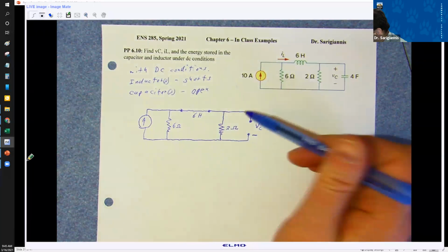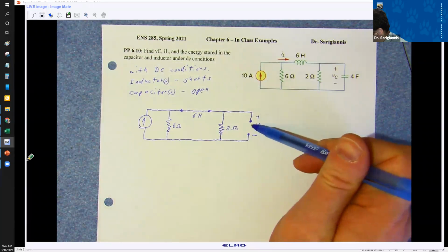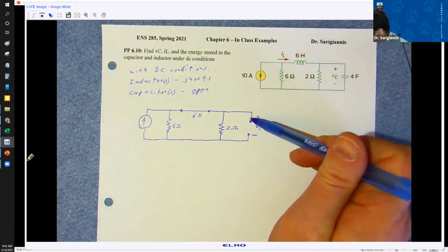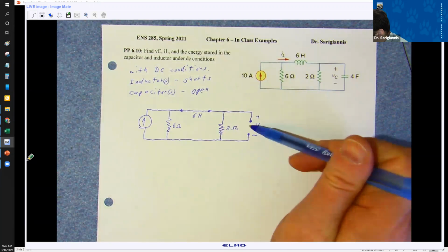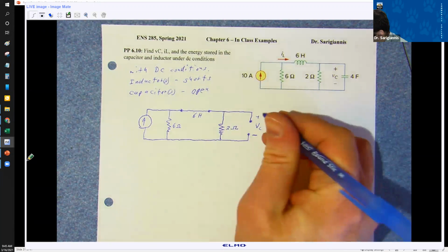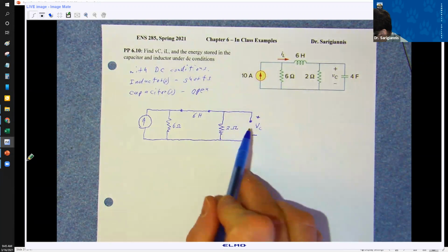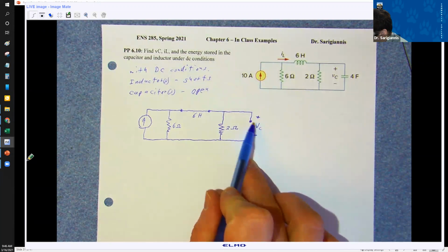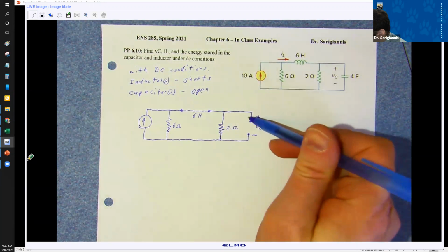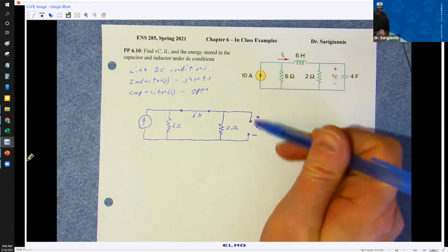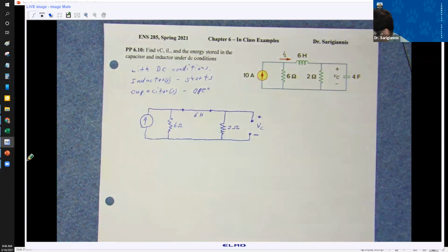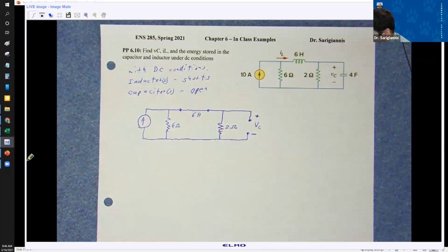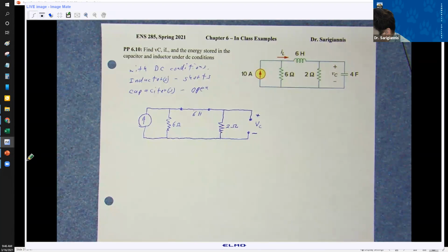Because there's a voltage drop, initially you get current flow, with positive charge flowing away from this end until the potential difference over the capacitor is such that you don't have enough voltage to drive any more difference in charge. So the capacitor is charging up. It's like a charged tank. It's full, so you're not filling it up anymore.